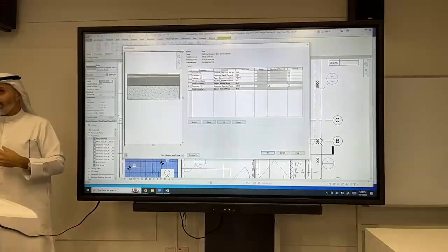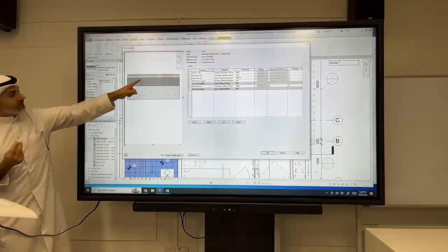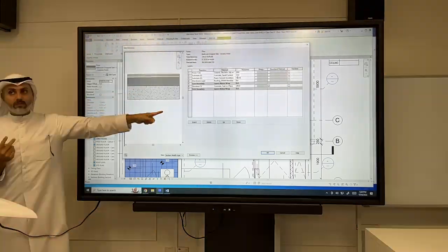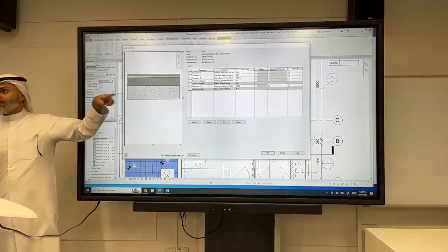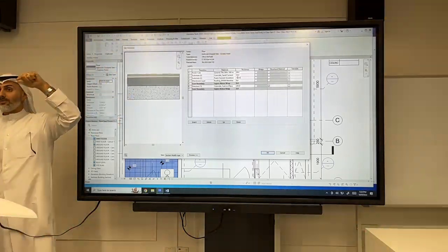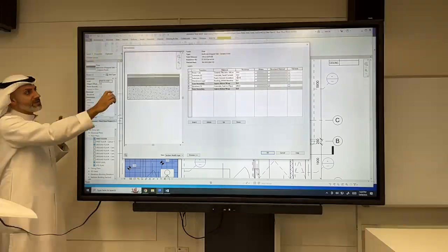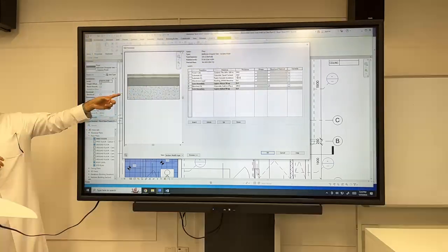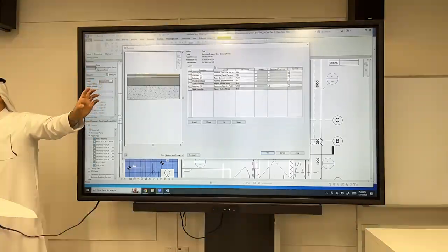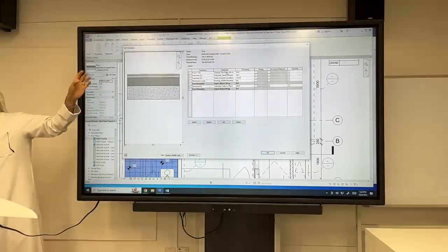That's one thing. The second thing is, when you put the pipe below, any water or any movement in the pipe, you will hear it from the room below. This way you're insulating the sound. Okay? So that's what we're doing. It's already there. You just have to change the ceramic finish from 300 to some other size.